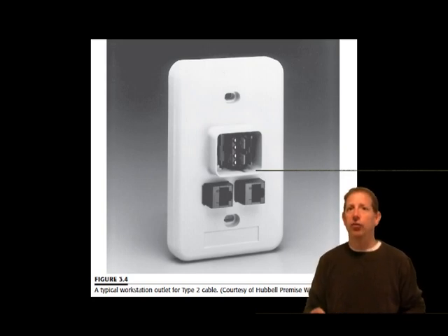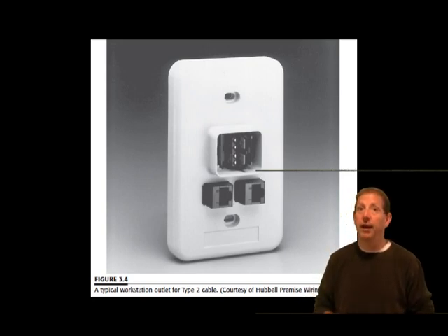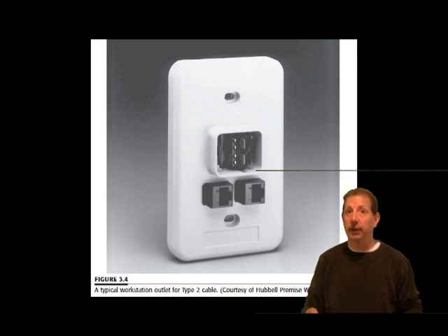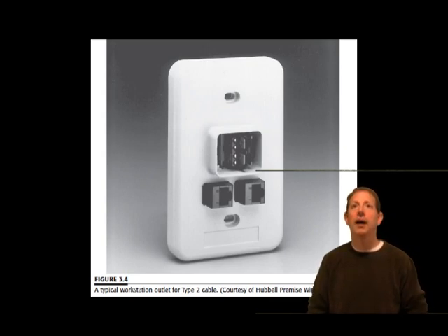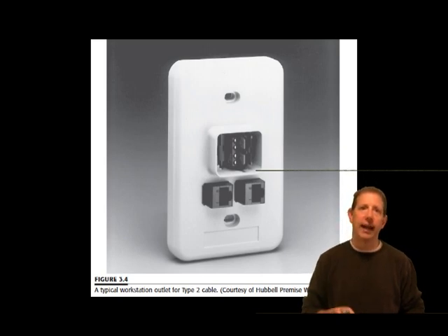Type 6 and 9 are 26 gauge non-plenum and plenum versions of Type 1 cable. Type 3 is 105 ohm, 24 gauge unshielded, twisted 4-pair cable that meets IBM specifications. It is available in plenum and non-plenum insulation and is similar but not identical to Cat 3 cable.